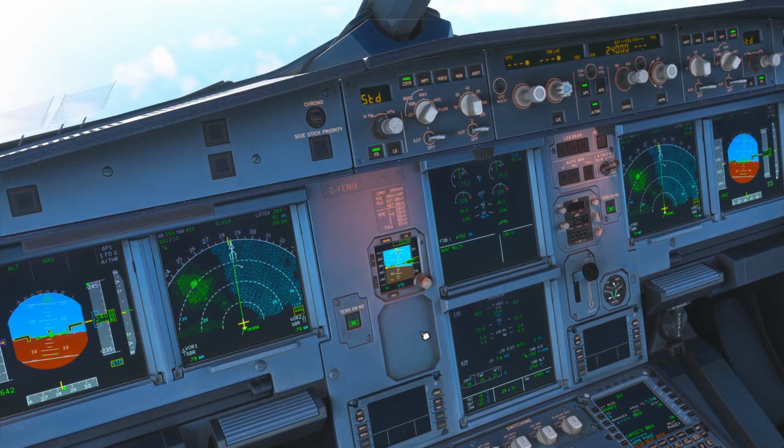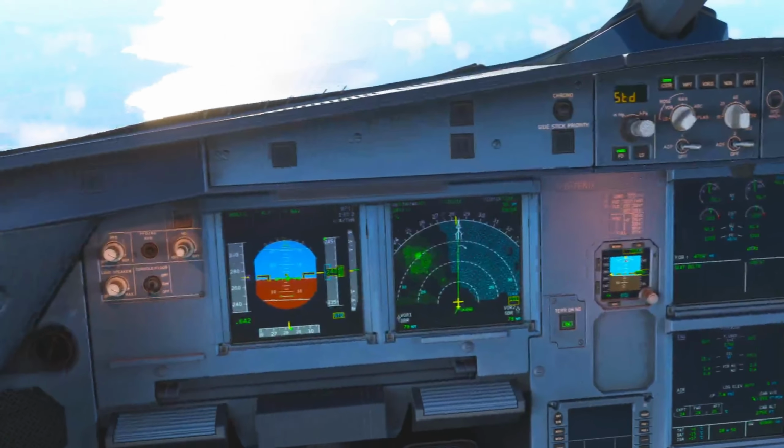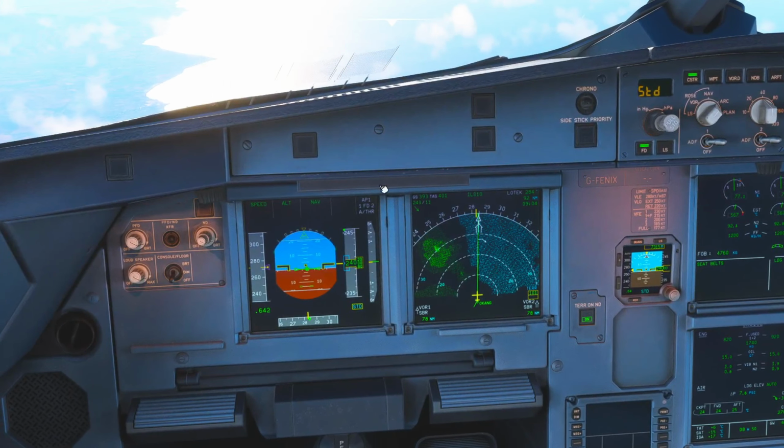Capture the ILS localizer and glide slope, shown on the FMA flight mode annunciator, and at 10 feet above the ground, when the retard and rollout are shown, pull the reverse thrust to idle. Disconnect the autopilot with the red takeover button on the side stick when the landing is finished or when you want to vacate the runway.